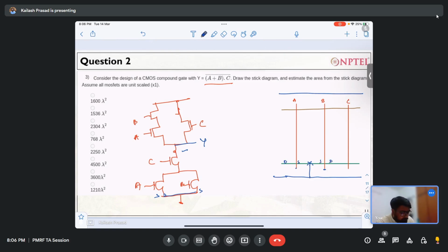So this is connected to ground. But the thing is, the drains are also connected. So then you have to make something like this. Then the drains are also connected. After that, you see this node is actually connected to the source of C. The source is already connected, but the drain is connected somewhere else. Where is it connected? A and C. We will do that, but before that, you can see that B and C have a common connection of VDD. So you can make a common connection of VDD. This is the source of both the transistors, connected over here.